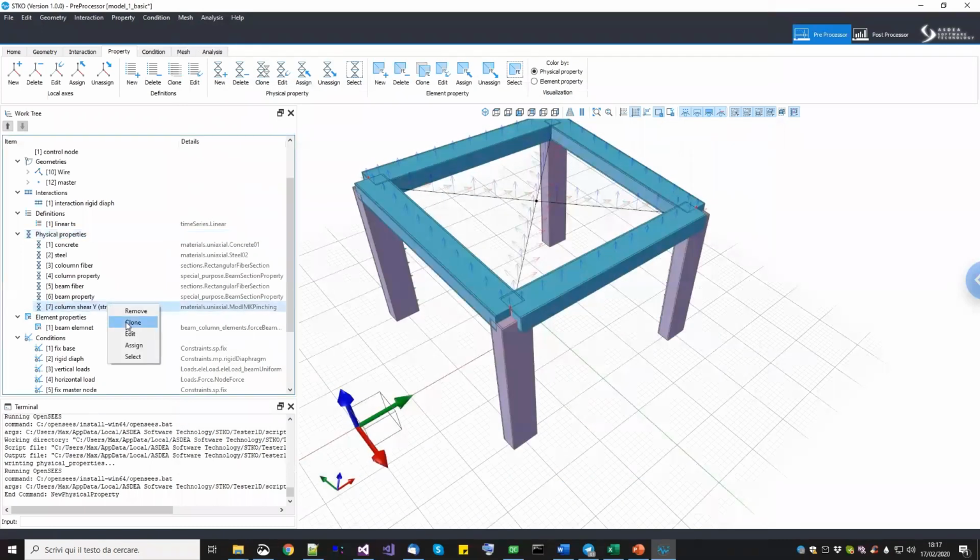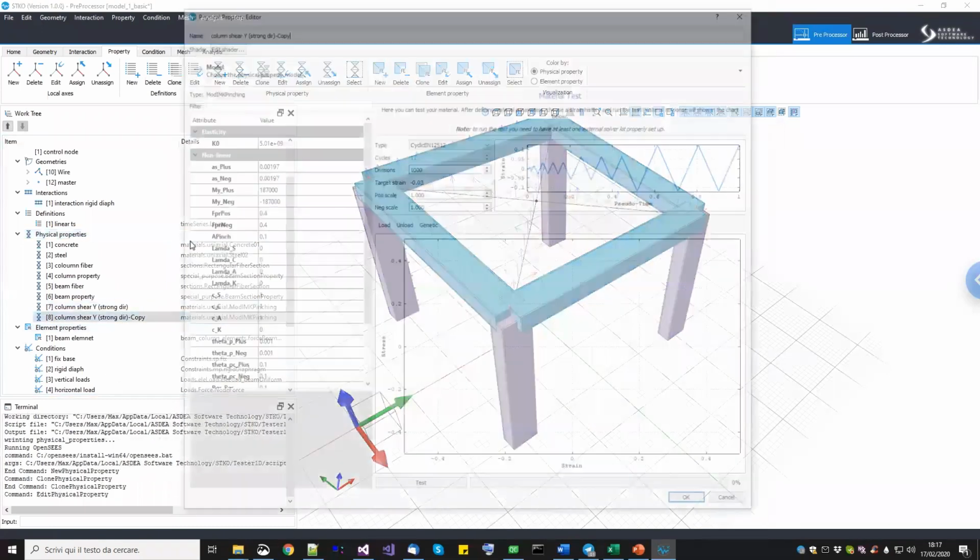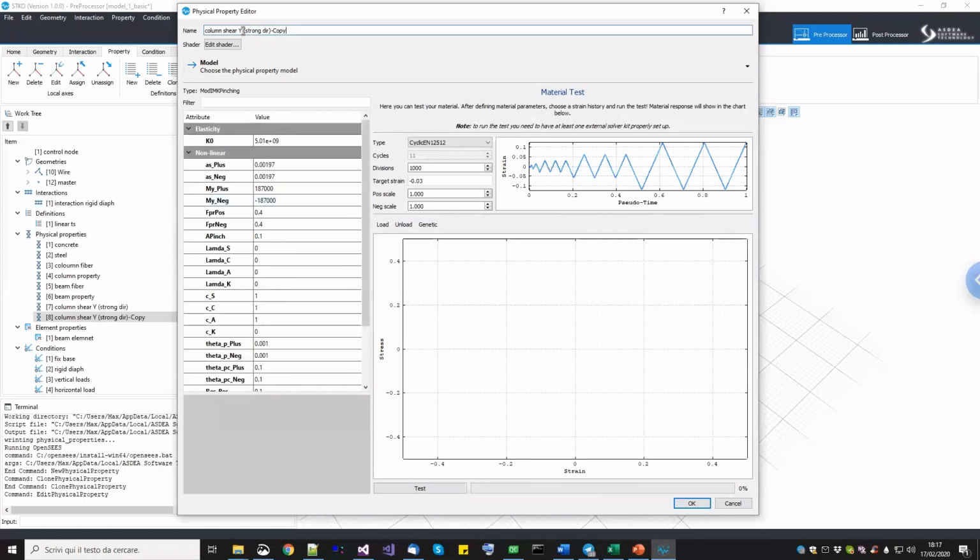Let's copy it and make the one for the width direction. As I told you, I inverted the property. So the strong direction will be the width direction, actually, just to be consistent with the file that I sent you. But it is not a problem, just an example. So width direction, same one, but we need to change some values. 0.0342.